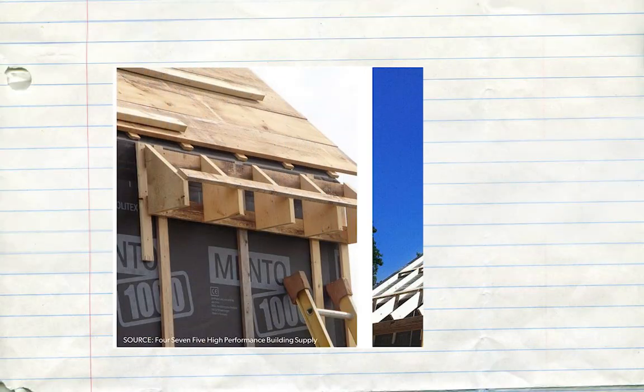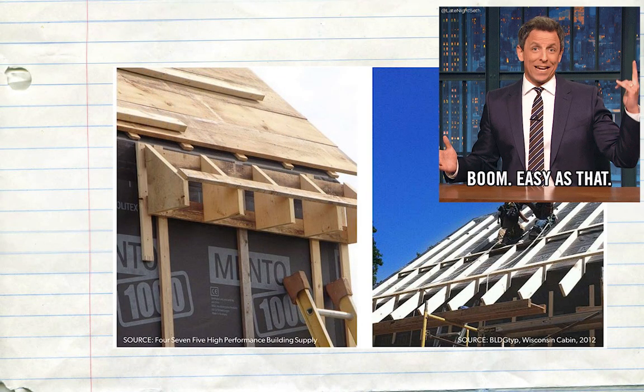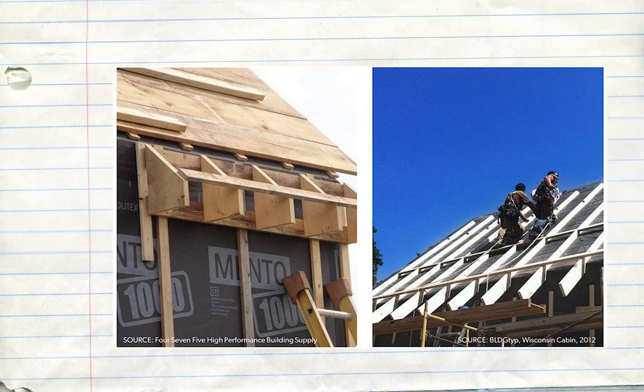Now let's talk about roofs. In places like here, for example, with a lot of precipitation, we love pitched roofs, but they can also mean a problem. What is a great solution? Well, you can use raised heel trusses, also called energy trusses, which basically elevate your roof so the thermal envelope remains continuous. Or use thermal bridge-free rafter tails, strong enough to support the roofing material, but let the thermal layer run uninterrupted.